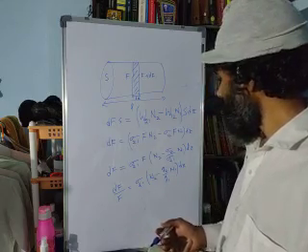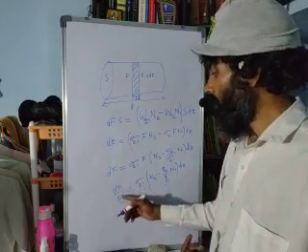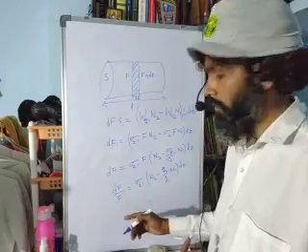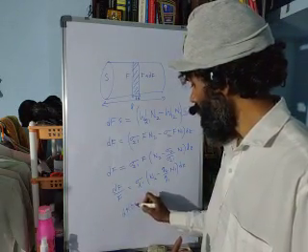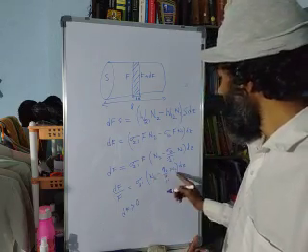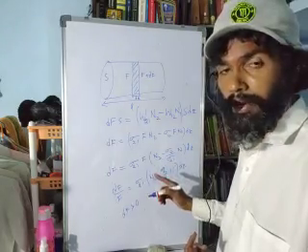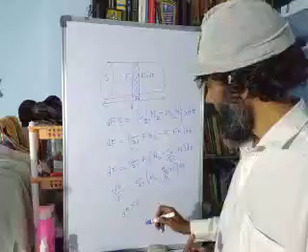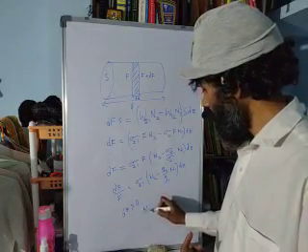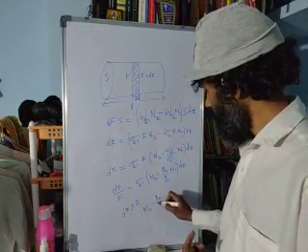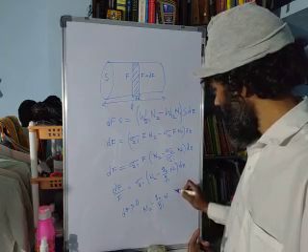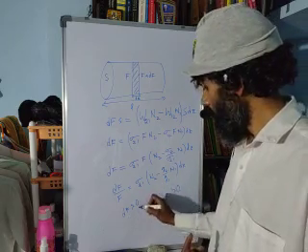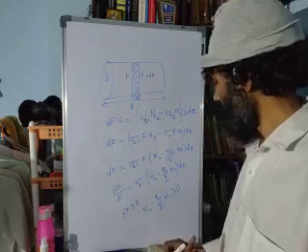But let me quickly see that to have this df quantity as a positive number, so to have this df greater than 0, I should expect this N2 minus the quantity in the bracket to be more than 0. That is, N2 minus Z2 by Z1 into N1 should be greater than 0 if we want to have this condition.